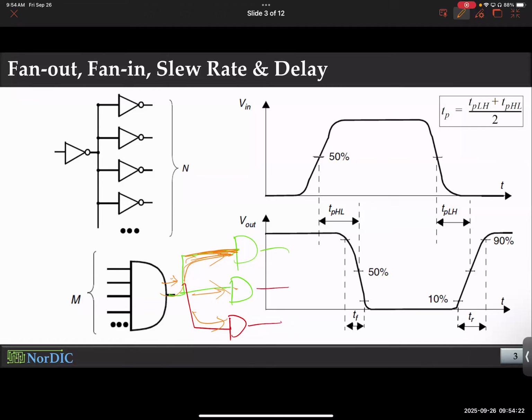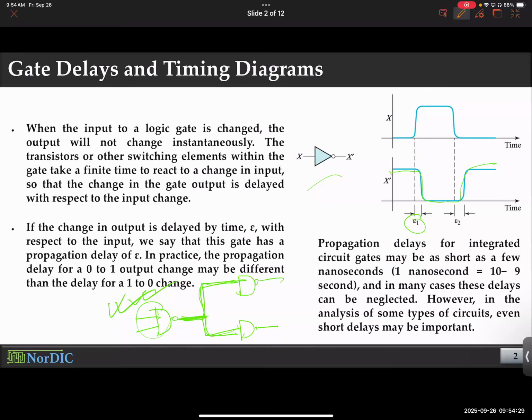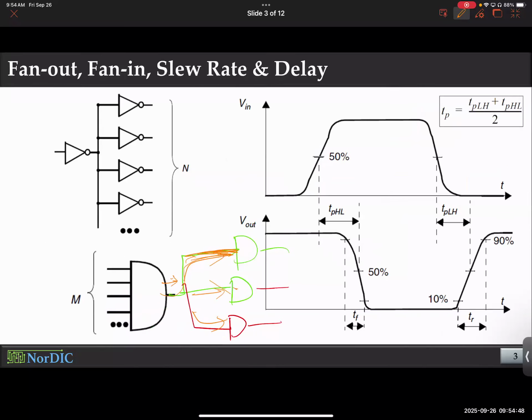Are you guys all with me so far? It's as if you're using 3 hoses on one outlet, right? You're trying to water 3 different sections of your garden, but you don't simply have enough water. You need more time, honestly. So basically, if you branch out, you have less current flowing through the branches. So it will take you more time to charge up the capacitors in every branch. That means your delay for the overall operation will increase.